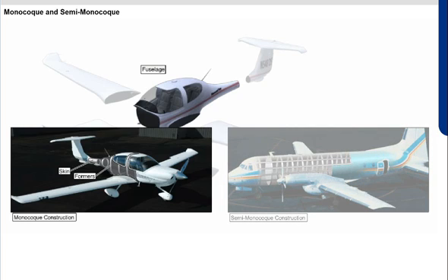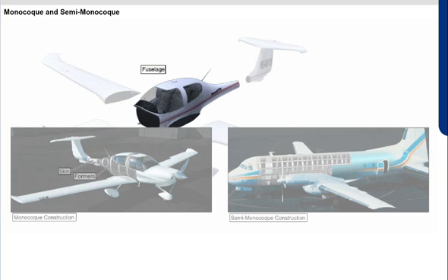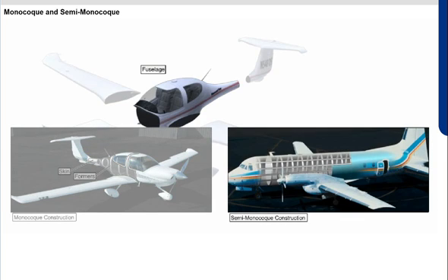The monocoque design uses the skin to support almost all imposed loads. The structure can be very strong, but cannot tolerate any dents or deformation of the surface. This characteristic is easily demonstrated by a thin aluminum beverage can. You can exert a large force to the ends of the can without causing any damage. However, if the side of the can is dented only slightly, it collapses easily. Due to limitations of the monocoque design, many manufacturers use a semi-monocoque structure. The semi-monocoque system incorporates a substructure riveted to the airplane skin to maintain the shape of the airframe and increase its strength.